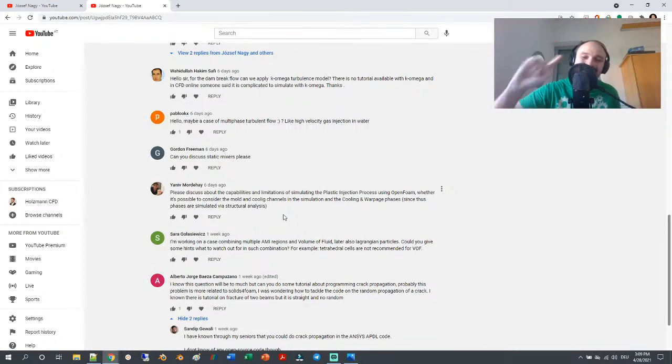And another point is the heat transfer from the melt to the wall. And what no one did up until now is the actual heat transfer throughout the solid wall in the tool. So the best approach would be to combine these plastic injection molding models with conjugate heat transfer, but that's a very high-end solution.